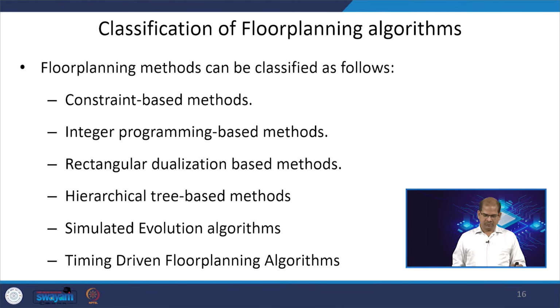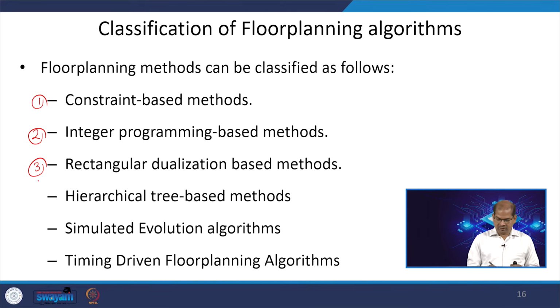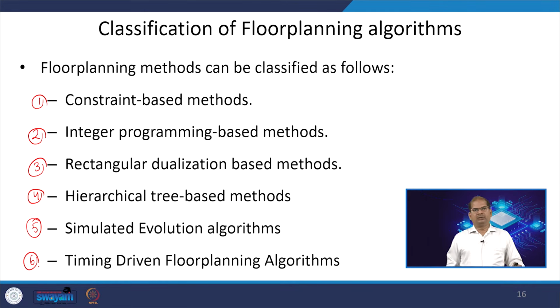We are just putting all these together in one of the slides. Here you can see we have constraint based methods, integer programming based methods, rectangular dualization based methods, hierarchical tree based methods, the simulated evolution algorithm, and the last one is the timing driven floor planning algorithm. So, there are 6 different algorithms. Floor planning is quite useful while designing a chip because it will optimize the area of